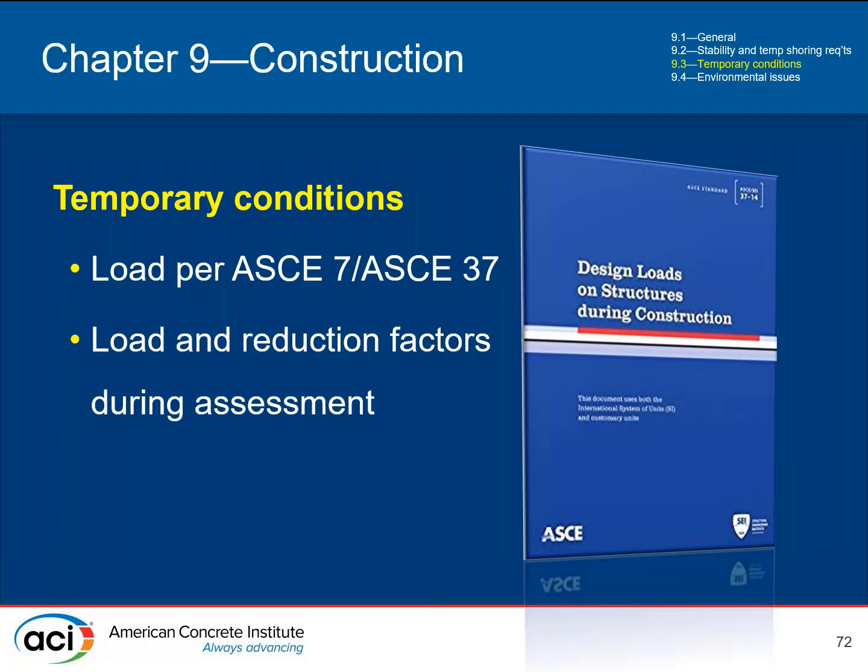What are the appropriate loads when it's not construction? You're dealing with a structure that has partial construction loads and partial normal loads. What are the appropriate load factors and loads in that situation? So it does get a little bit trickier in many ways during a repair project.